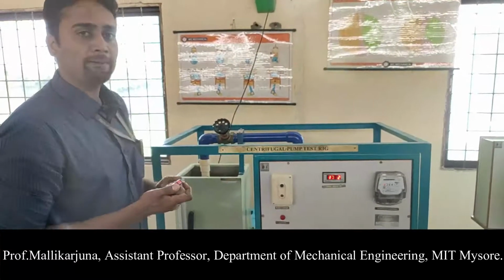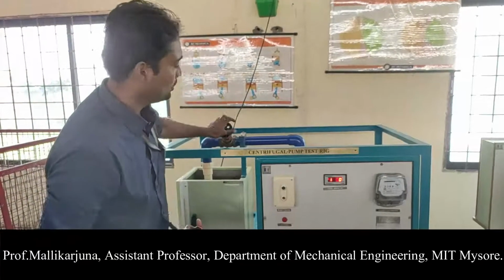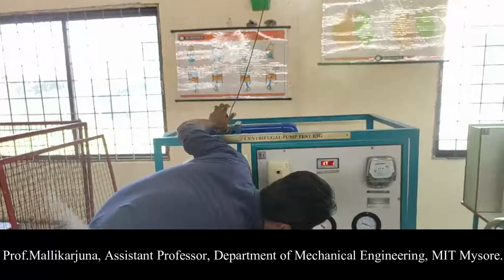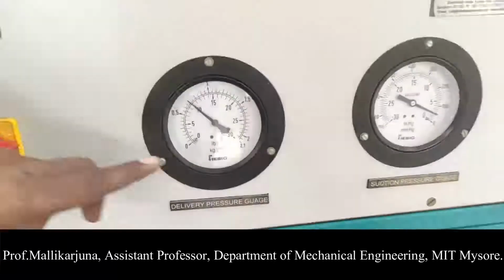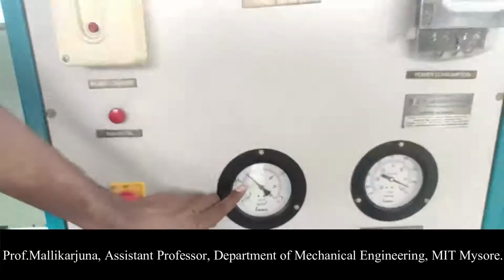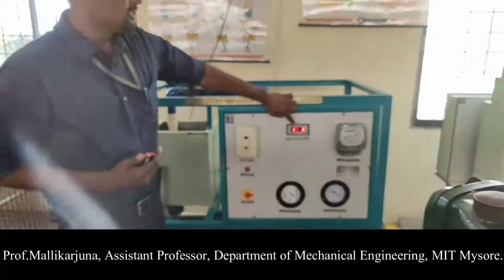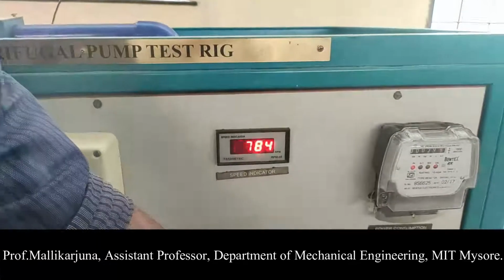Now if I have to repeat the trial, I need to adjust the delivery pressure from 0.6 to 0.7. Please open the valve, clear data now. So now the pressure is 0.7 kg per centimeter square. I am conducting the second trial for 0.7 kg per centimeter square. Now this is the speed with which the belt is running, and this is the suction pressure.